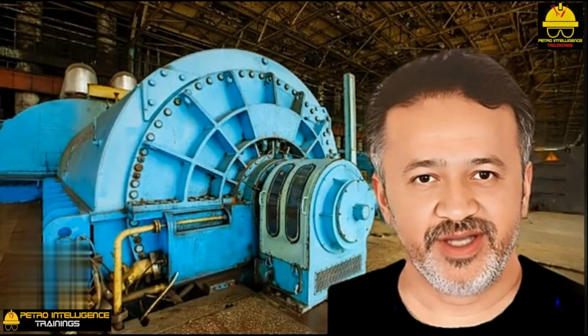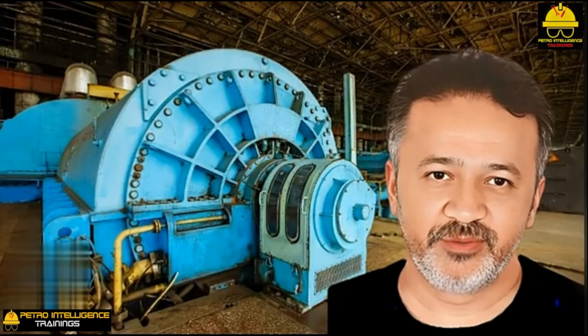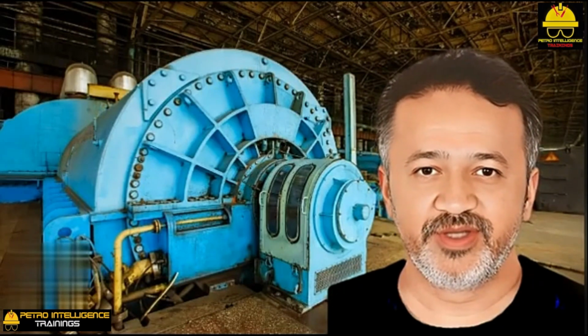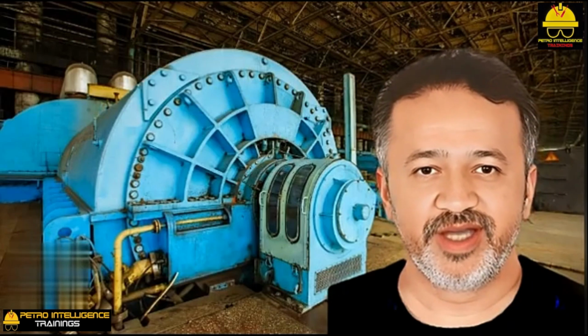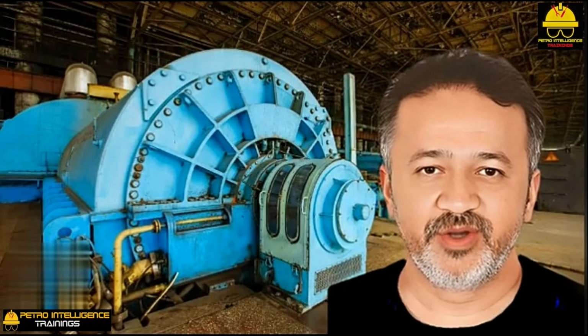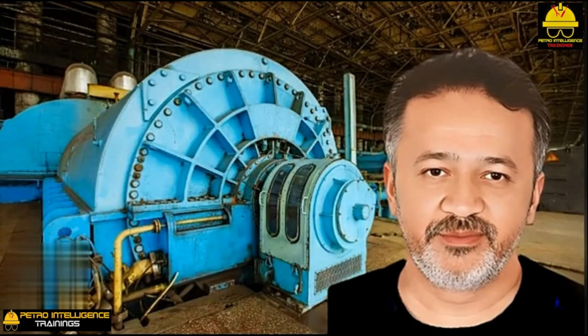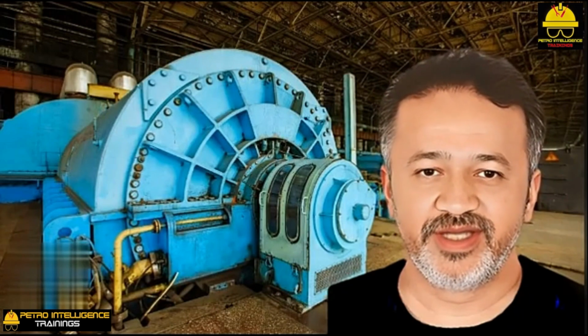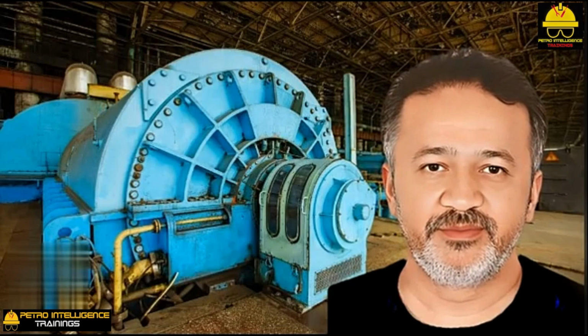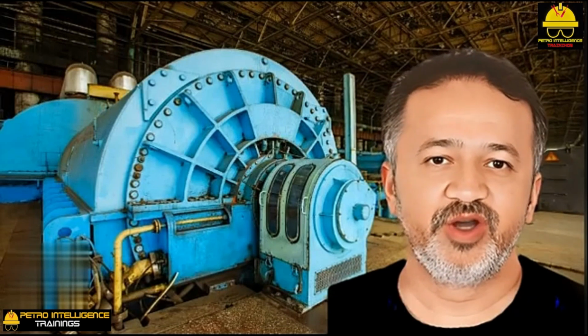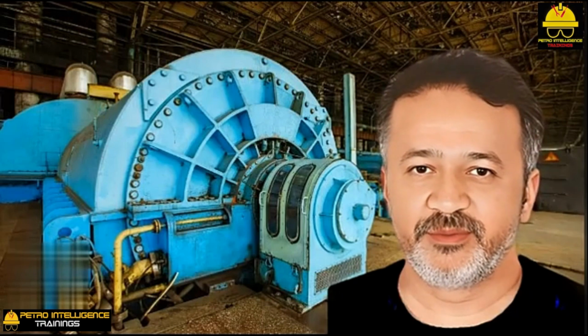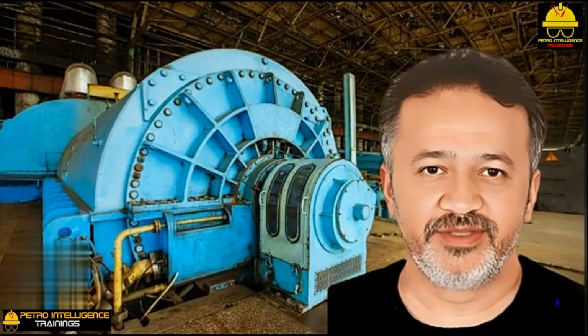Turbines are widely used in process plants to drive everything from 2 horsepower pumps to 20,000 horsepower centrifugal compressors. They are versatile machines, in that they are intrinsically variable speed devices. Electric motors are intrinsically fixed speed machines. It is true that there are a variety of ways to convert AC, alternating current, motors to variable speed, but they are all expensive and complex.